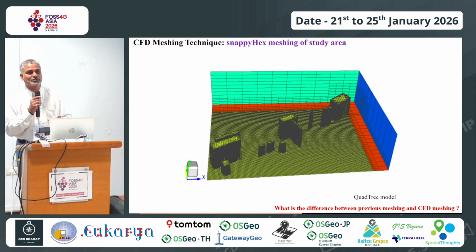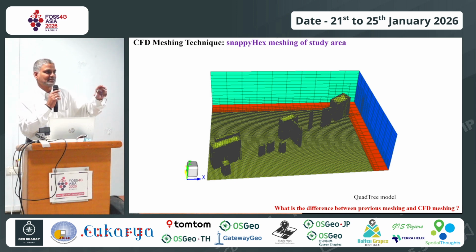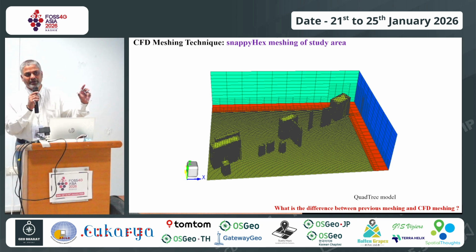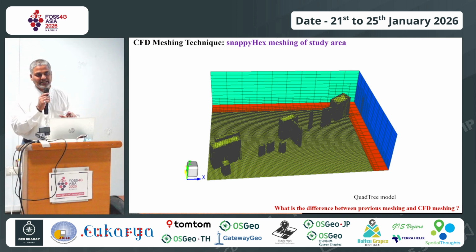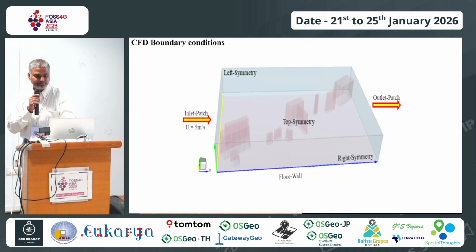There is an open source tool called OpenFOAM. That is the #1 open source tool in CFD, and as of now I'm not finding any equivalent tool. In pre-processing, there is something called meshing. Whatever STL file you give, it will be divided into a mesh, and there are n number of meshing parameters. I decided on snappyHexMesh because I want to get results in the quickest possible time. That is one of the reasons I took snappyHexMesh.